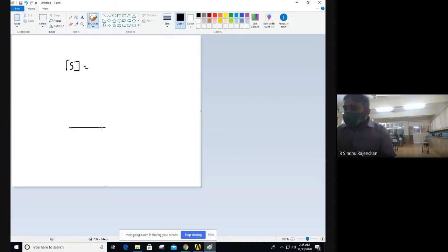I'm going to assume some port numbers, but be careful when you're simulating it. In the lab, if it is a different port number, then this S matrix will change accordingly. Let me take this as 3, this as 4. You can take any numbers, but the same thing should be reflected in the S matrix. Since it's a 4-port device, I have a 4 cross 4 matrix, and all ports are matched, so diagonals are 0.